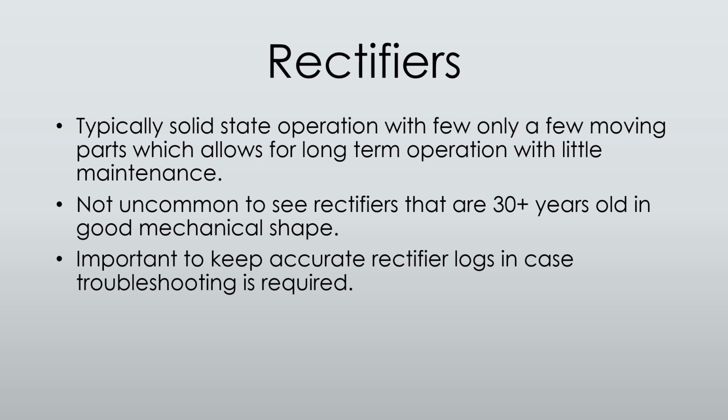Rectifiers are typically solid state in their operation with only a few moving parts. Typically the clock gauge would be the only moving part. This allows for long-term operation with little maintenance. It is not uncommon to see rectifiers that are 30+ years old in good mechanical shape. It is important, though, to keep accurate rectifier logs in case troubleshooting is required.